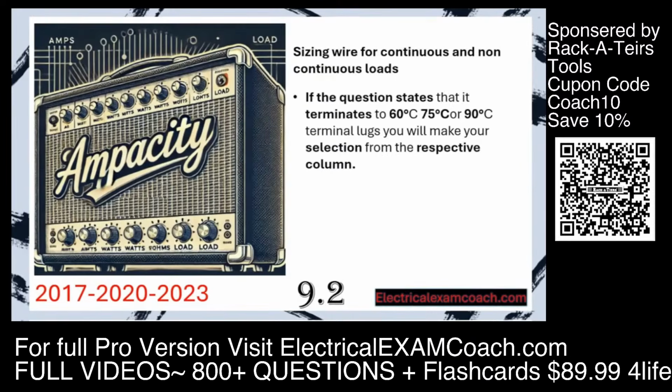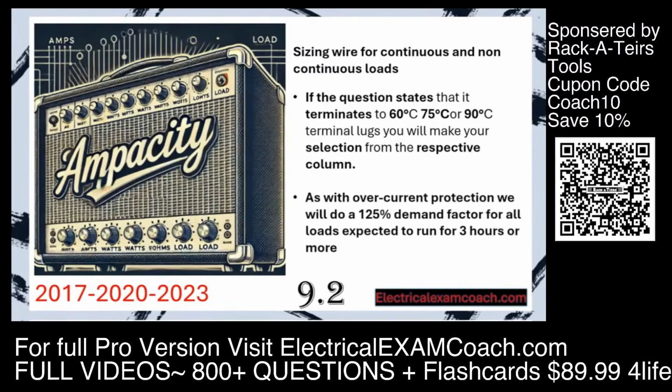Let's recap on the basics before we get started. If the question states that it terminates to 60, 75, or 90°C terminals, we're going to make our selection from that respective column under normal circumstances. And the second one is, as with overcurrent protection, like we learned before, we're going to do a 125% demand factor for all loads that are expected to run for 3 or more hours.